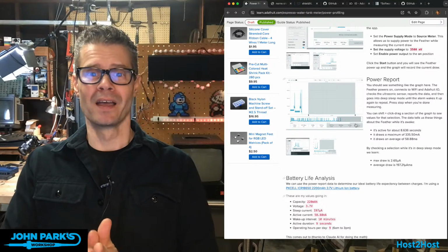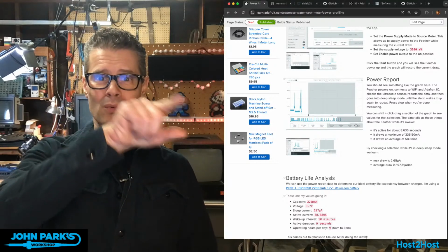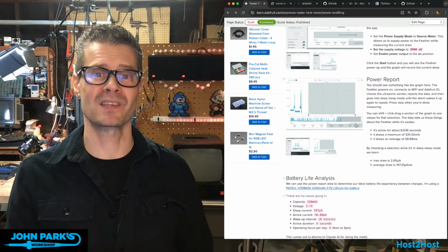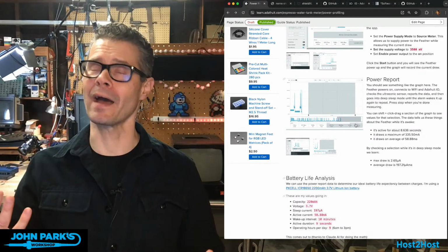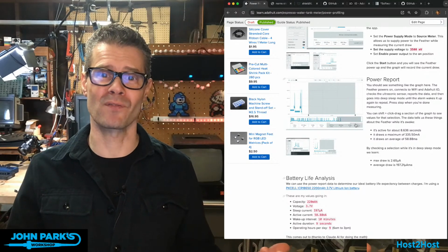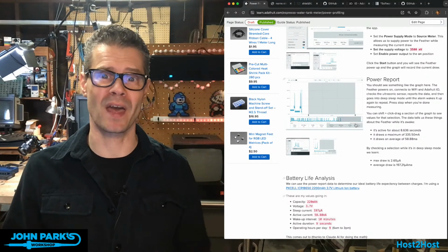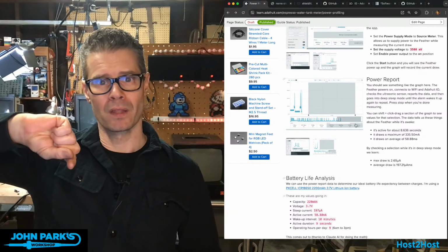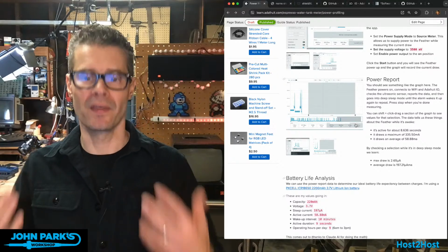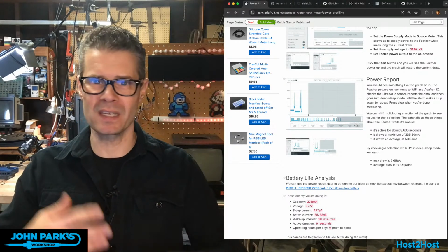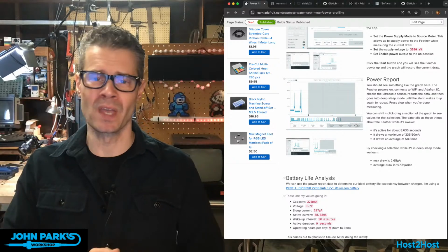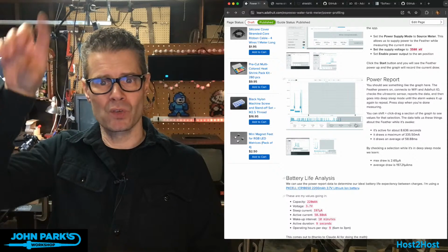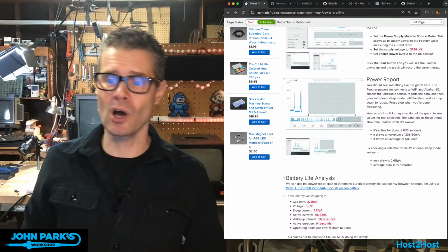Limor said you can get this a lot lower. I said, oh? She said, yeah, don't use the 3-volt power pin on the Feather for your sensor, because that means it is always powering the sensor. Oh yeah, that's just this 3-volt thing. If the Feather has any power, deep sleep doesn't turn that on and off. So we essentially needed to have deep sleep be able to control the power going to the little sensor, and that's why I'm now on pin A2. Any GPIO pin that can do digital would work. So now we set that pin high when we want to use the sensor, and when we go to deep sleep, we set it low.